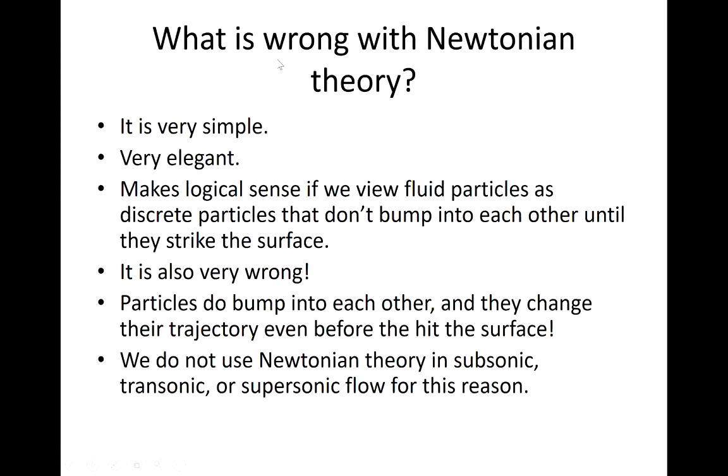So what's wrong with Newton's theory? It's very simple, very beautiful, very elegant. It makes logical sense if you view the fluid particles as discrete particles that don't bump into each other until they strike the surface. But it's also very wrong, because particles do bump into each other. They change their trajectory long before they hit the surface. Therefore, we cannot use Newtonian theory in subsonic flow, transonic flow, or supersonic flow.